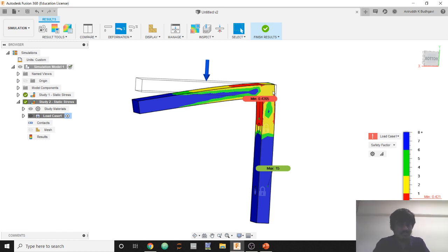That is because 3D printing is not a usual way of making things. There are some differences. It is literally adding layer on top of layer of plastic. So sometimes the layers don't have enough cohesion, and in that direction the actual stress it can take is sometimes very less.